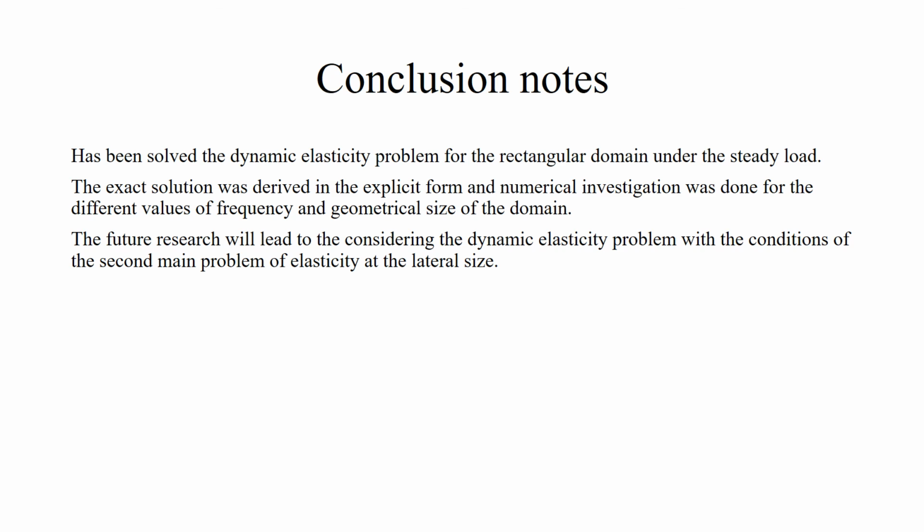Finally, let's sum up. What has been done? The dynamic elasticity problem for the rectangular domain under the steady load has been solved. The exact solution was derived in the explicit form, and numerical investigation was done for different values of frequency and geometrical size of the domain. The future research will lead to considering the dynamic elasticity problem with the conditions of the second main problem of elasticity at the lateral sides.